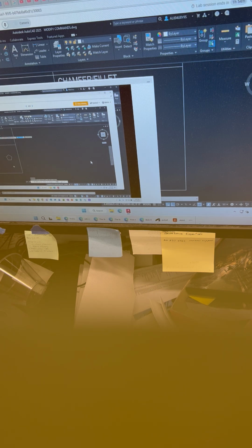All right, now click on the polygon that's already there. Now you have to pick on the side there first. You have to hover, yeah, and there, that'll work. You see how you see the grip? Now go ahead and click. Now, this time do circumscribe. Now point your cursor straight down and type in 1 foot. That's the same radius you had the last time. Type in 1 foot and hit enter.